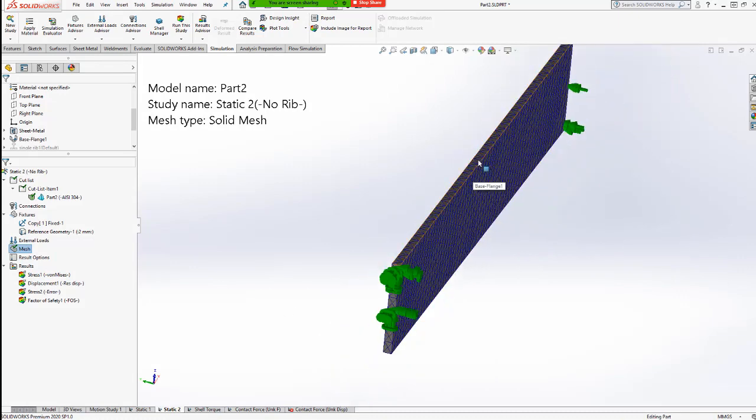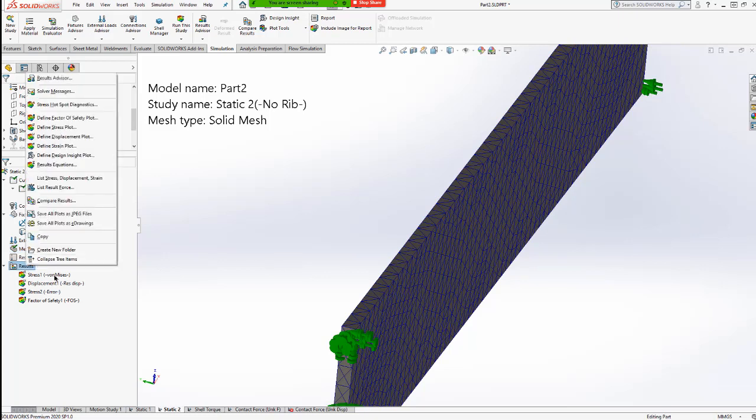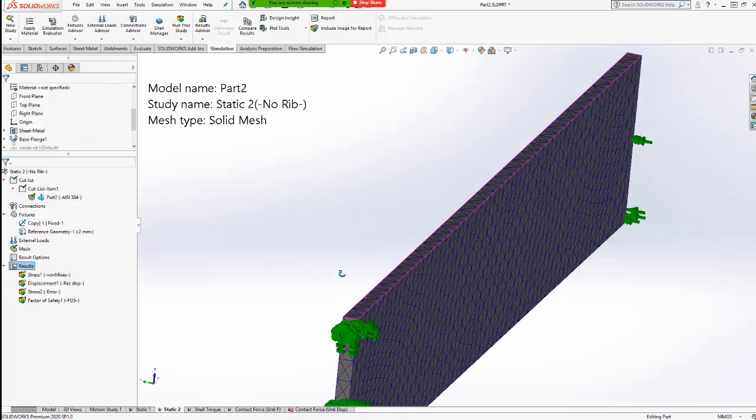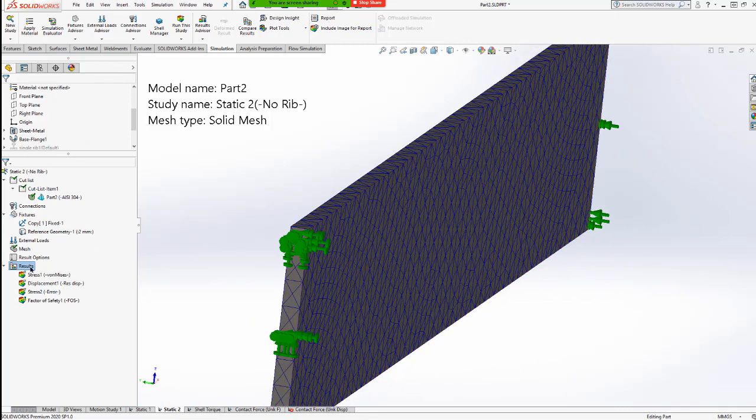So we can already see that, for our first analysis, this is not a lot of elements through that. And we're just going to keep that in mind, because a more refined, higher quality, or finer mesh definitely gets us better results because we're allowing a lot more elements. Of course, there are computational resources to consider at the time. We have to take these things into consideration before we just converge on an answer and call it good.